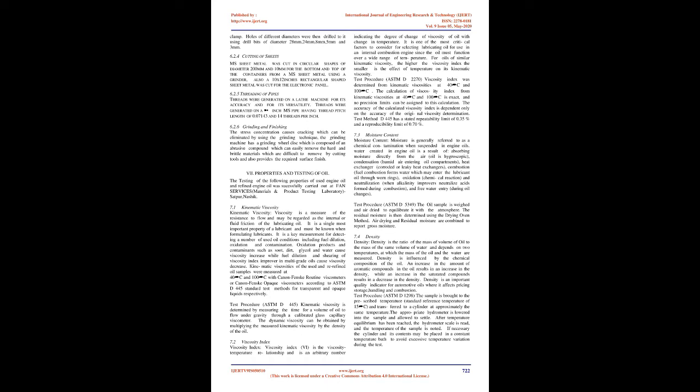7.2 Viscosity Index. Viscosity index, VI, is the viscosity temperature relationship and is an arbitrary number indicating the degree of change of viscosity of oil with change in temperature. It is one of the most critical factors to consider for selecting lubricating oil for use in an internal combustion engine, since the oil must function over a wide range of temperature. For oils of similar kinematic viscosity, the higher the viscosity index, the smaller is the effect of temperature on its kinematic viscosity.